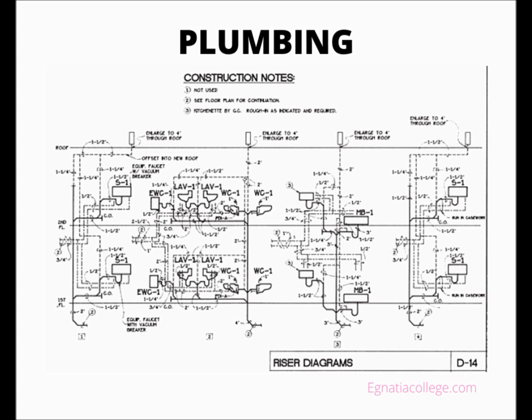The hot and cold water piping is similar to that found in homes, except that the hot water is a two-pipe system. A return hot water pipe allows the hot water to circulate continuously, ensuring that hot water is readily available at the point of use. The hot water supply and hot water return can be distinguished from each other by the number of short dashes in the symbol.